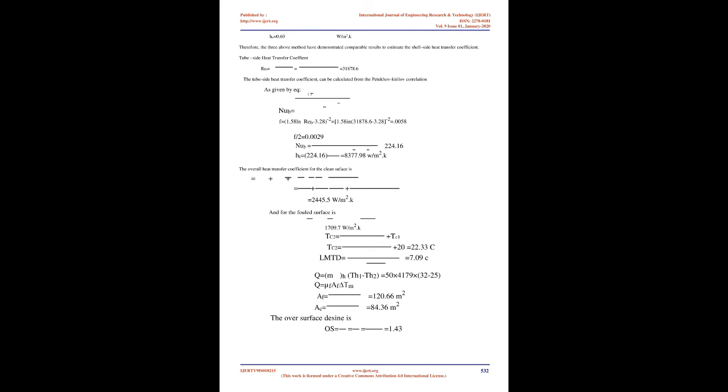If the first design was inadequate to meet the required heat load, it is usually necessary to increase the size of the exchanger, while still remaining within specified or feasible limits of pressure drop, tube length, shell diameter, etc. This will sometimes mean going to multiple exchanger configurations. If the first design more than meets heat load requirements or does not use all the allowable pressure drop, a less expensive exchanger can usually be designed to fulfill process requirements.